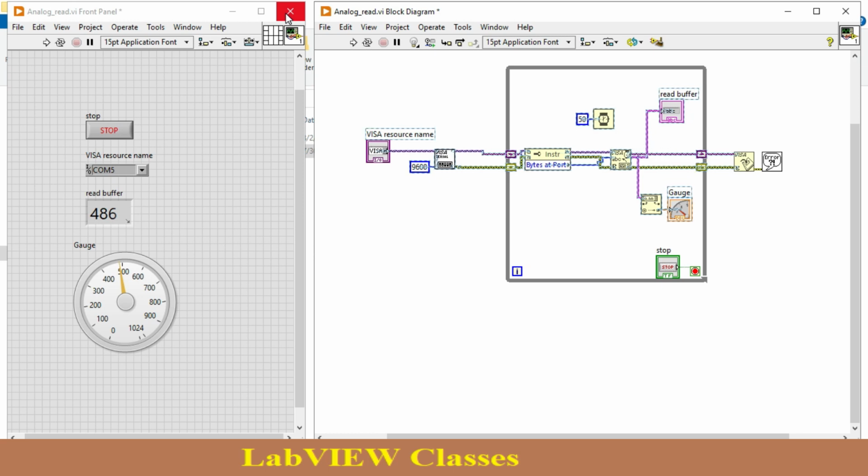I have some issue with the drivers for my company work. Can you help me with how to combine the programs for the LabVIEW programs? For example, in the AC source, we need to set voltage, frequency, and then turn on, three sequences. The driver I downloaded from the AC source website, they have separate programs.